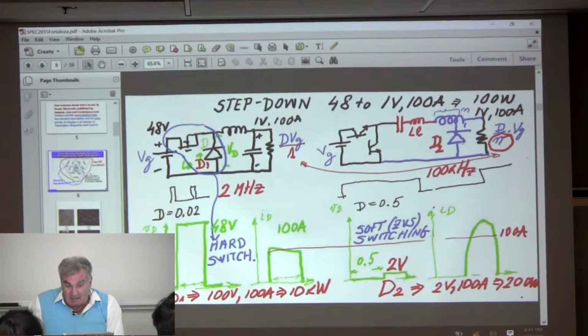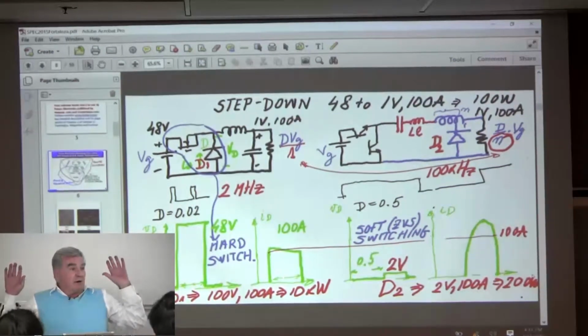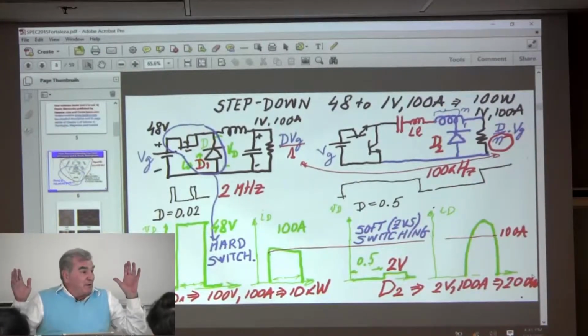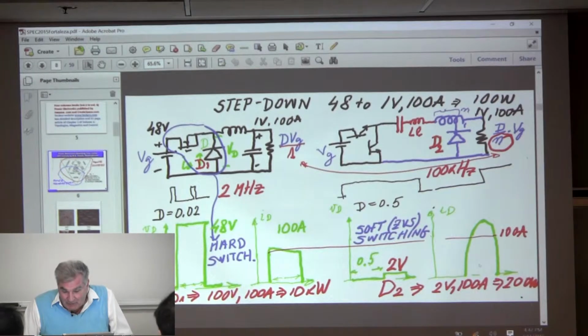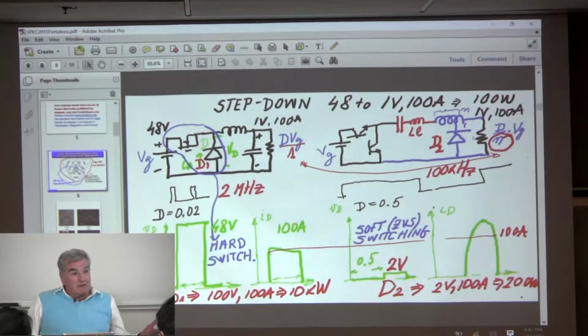It starts, this current diode says, in this loop, transistor and diode in series, and when this current goes to 0, this diode doesn't let the current go negative. So I stop here, I'm sorry, can't deliver anymore. Which is great because automatically stops where it should, right? So now you deliver a pulse of the current and this diode doesn't even know that it's switching, right?